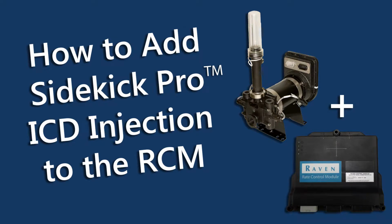Today we are going to discuss how to configure RCM with ICD Injection pump to ensure that the ICD Injection pump shows up as product 2 within the RCM object pool. For this demonstration, we are going to set up with a Viper 4 field computer. I'm going to walk you through the steps, what to expect to see and what settings need to be adjusted in order to do this.